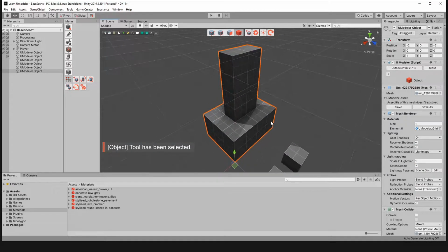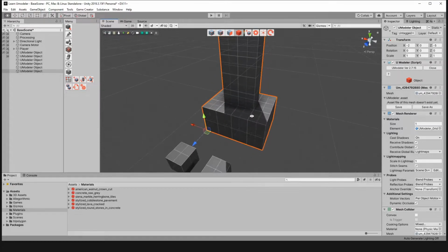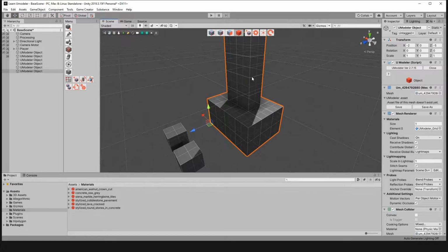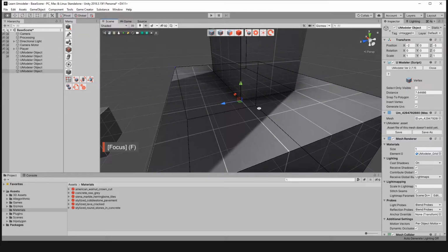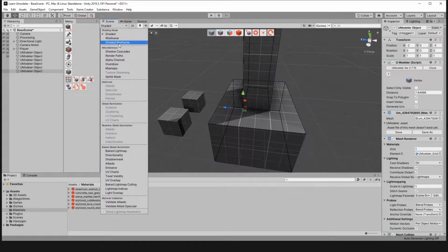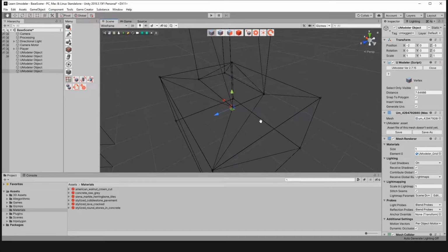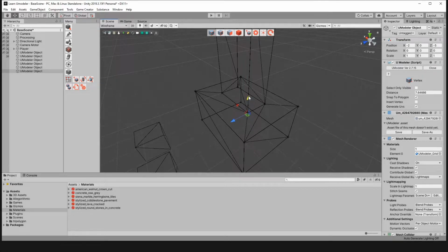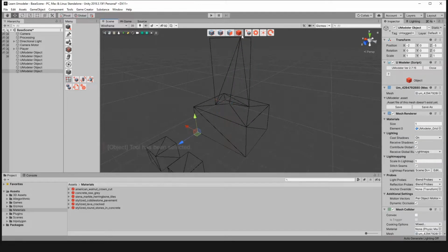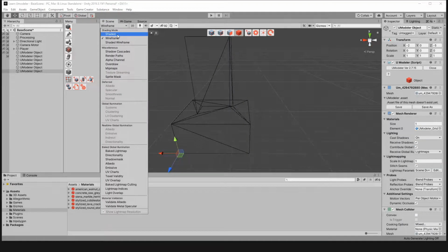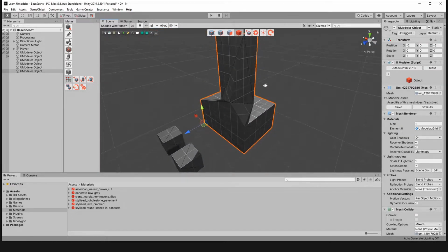And in this case, you actually are going to have one object because you are still connected to that original drawing object. So if we were to look at the verts, I believe this is pretty much all still connected. And I'm going to go ahead and go into wireframe. So it looks like it creates a merge operation during that. And so now this is one object. And that actually could be beneficial in a lot of ways. It just really depends on what you're going for and how you're building out your object.